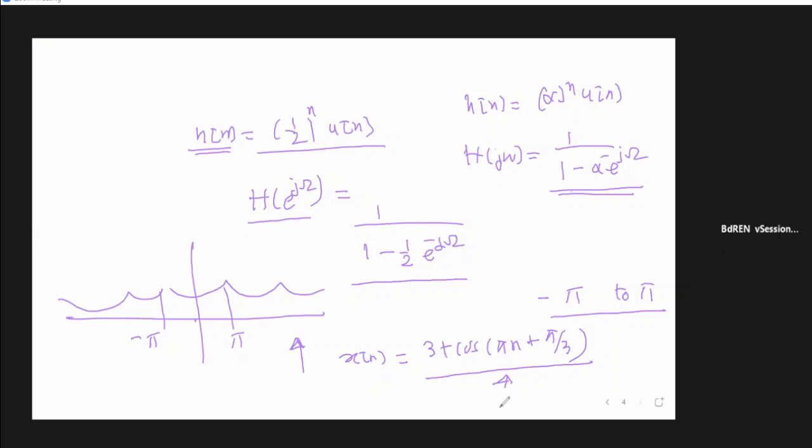Then if these frequencies are present there, can you identify which of the components we will be getting at the output? You see that the region from minus pi to pi also contained a DC part at omega equal to 0, isn't it? So a DC part will appear in your output. Similarly, this signal is also appearing in the output. The reason is that it is within the frequency band of your H(e^{jω}), isn't it? But some scaling factor, gain factor will be there that you have to find out, okay?